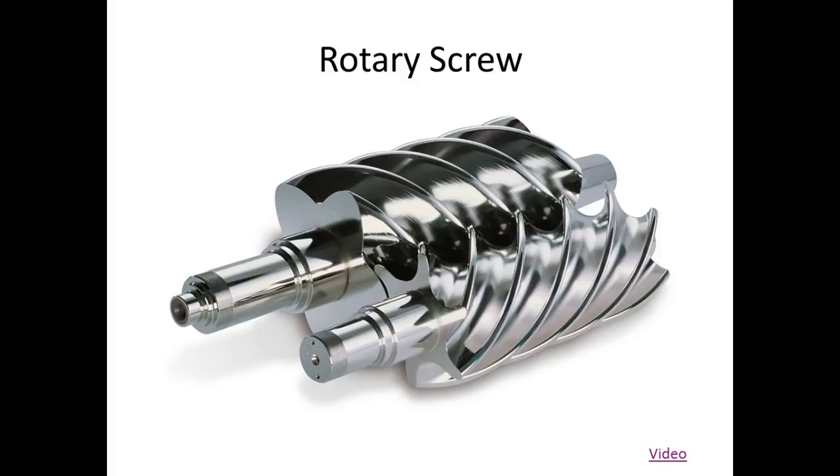Most of your reciprocating compressors, what do we have to do with those? We have to store it in a tank. And if we didn't use a tank, then what would happen is our air would do what? It wouldn't be a smooth flow. You would only generate air on the compression stroke of your piston, and so it would jerk. So normally what we do to compensate for that, of course, is we take the output of the reciprocating compressor and put it in a tank. So your tank is only doing the pulsing, and then you get a pretty even flow coming out of your tank.